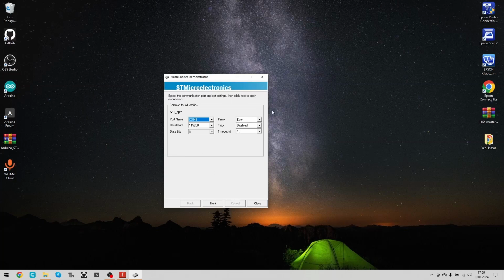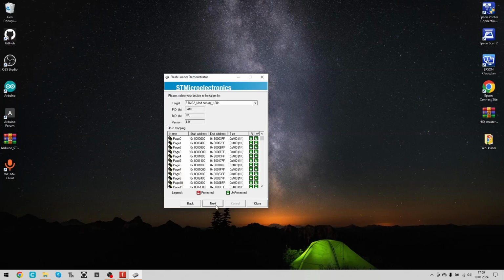Then I click next. Next. We should pay attention here again. If your board is STM32F103C series 8, you choose 64K. Else you choose 128K. I choose this. Next.